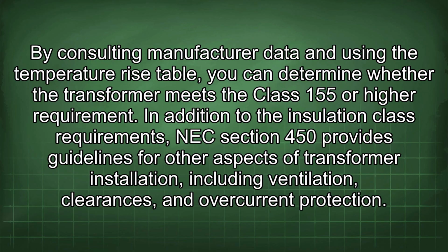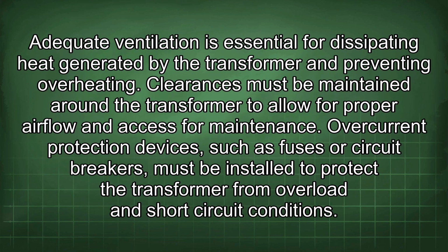In addition to the insulation class requirements, NEC Section 450 provides guidelines for other aspects of transformer installation, including ventilation, clearances, and overcurrent protection. Adequate ventilation is essential for dissipating heat generated by the transformer and preventing overheating. Clearances must be maintained around the transformer to allow for proper airflow and access for maintenance.